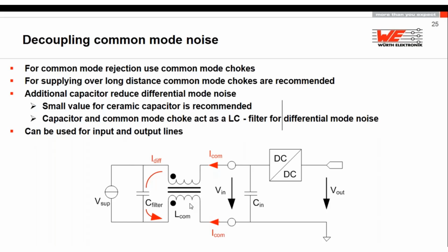You can make a star distribution, but take care that no I/O are allowed that make any connection around the common mode choke. It must take its ground from the common mode choke, because otherwise it will not have a correct compensation and it will not be effective. This is good for common mode noise.